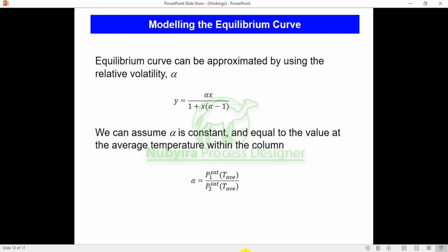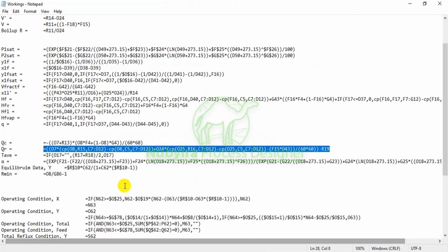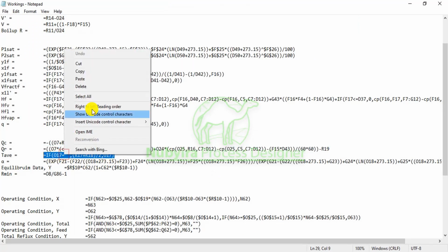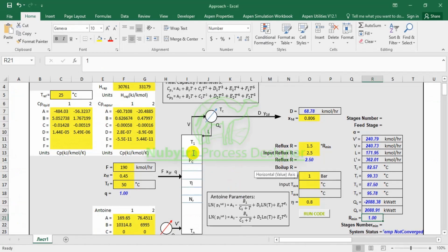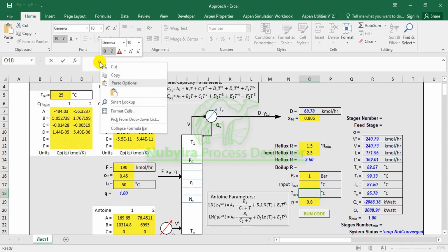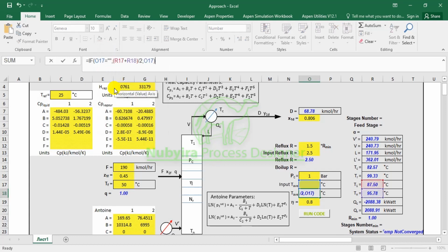And so my formula for the average temperature is basically the mean of the top stage temperature and the last stage temperature, because the temperature will be interpolated for the number of stages that we have. Since we are not calculating temperature for the other stages, we can just use this value. And the if statement is there, assuming you want to put your own average temperature, you can easily override the one it is calculating and it will work.